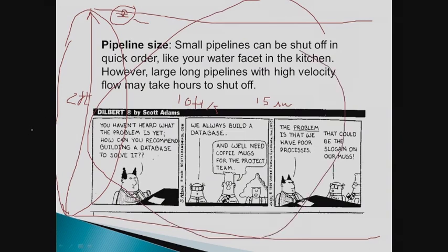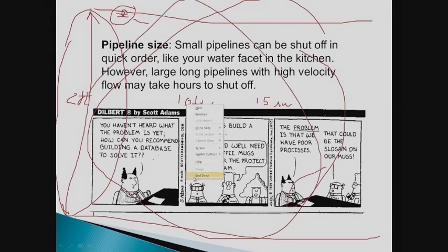You will spend maybe an entire morning. You may have your crew there. They get up and turn the valve 1/4 turn, maybe not even that, and then they'll sit down. 15 minutes later, they'll get up, turn it another 1/4 turn, and then they'll sit down. They do this every 15 minutes or so, and eventually they'll get the pipeline shut down.